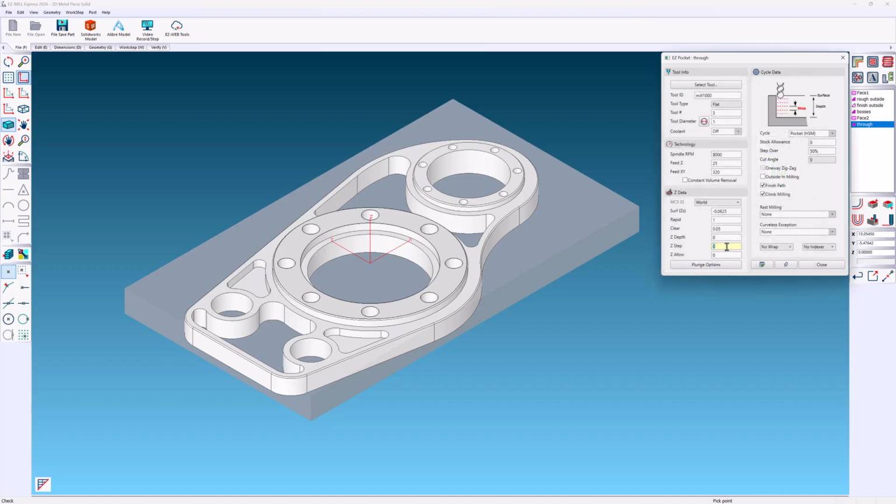The pockets are pretty deep, so we will remove the material in layers, using a Z-step. Let's also add a plunge to gradually feed into the material for each step. This helps clear the chips and takes the stress off the cutter. For this example, I will choose helical. The helical radius is the value measured from the center of the cutter. The end mill will advance 50 thousandths in Z for each revolution.